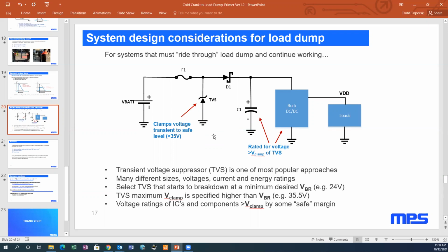So those are all critical. And then the current and voltage rating, as well as the energy rating, will also dictate how large the package is. So SMA will be one of the smaller packages, and then you can get SMB, SMC, and so on. So the amount of energy that needs to be withstood will determine ultimately how big your package needs to be.